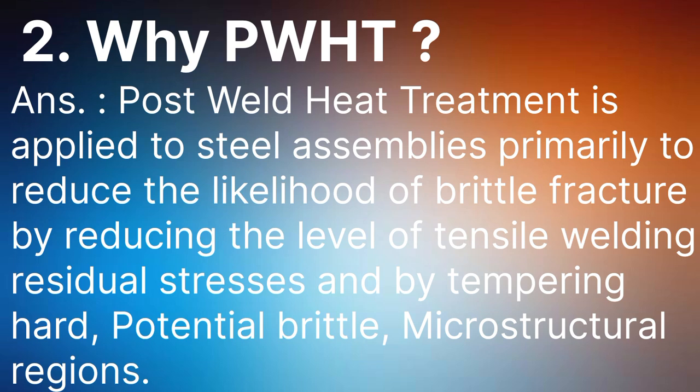Additionally, PWHT can also lead to metal strength enhancement and hardness reduction. Stress relieving and post heating are the most commonly used PWHT procedures. Application and code requirements as well as service environment primarily drive the need for PWHT.